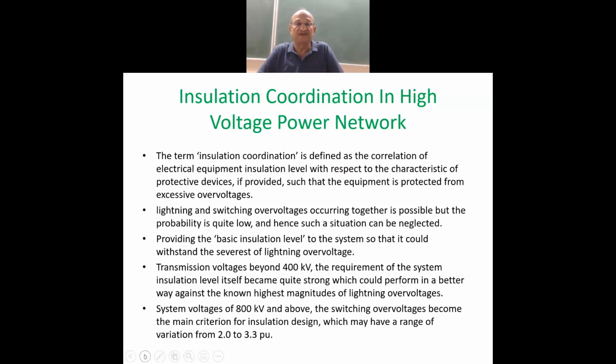Pellets or blocks of zinc oxide were brought together to the required number, and there was no air gap between two electrodes in these newer types of lightning arresters, and they function more reliably than the earlier types.